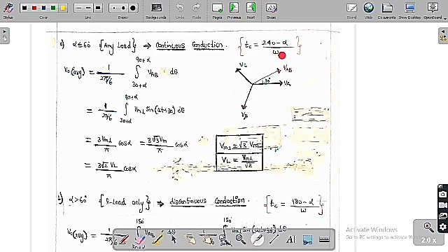So listen carefully. Out of 360, 120 degrees is the conduction of each thyristor. Therefore the remaining angle is 360 minus 120, which is 240. Out of that, alpha is the angle for which they face the forward blocking voltage. So the remaining angle is 240 minus alpha. In this range of angle they face the reverse voltage. So 240 minus alpha by omega.